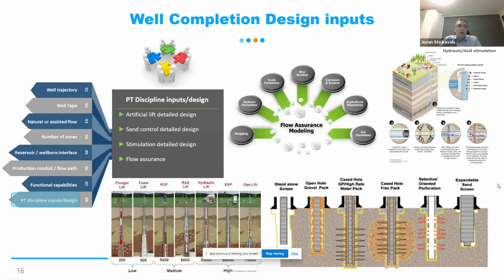So, for example, if the well will be drilled across some geological formation which is very tight and requires hydraulic pressure stimulation, then you know how you will complete this reservoir section, and you will maybe insert fracturing sleeves, across which you can do fracturing by compartments.